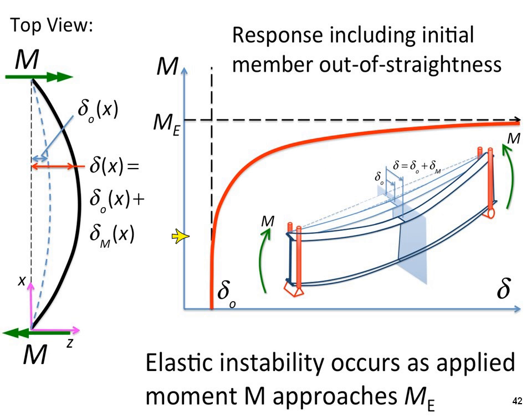So the bottom line here is that for beams, at least, AISC does not really get too excited about this initial imperfection, but it is there. And if you were to do an elastic analysis and gradually apply these moments, the buckling load would approach the elastic bifurcation moment that we just computed. So this is the difference between instability and bifurcation. Instability is some type of imperfection grows until it becomes unbounded, versus bifurcation, where you either have no deflection or you've got an unlimited amount of deflection. So that's the impact of an initial imperfection: it causes minor axis bending and some twist.